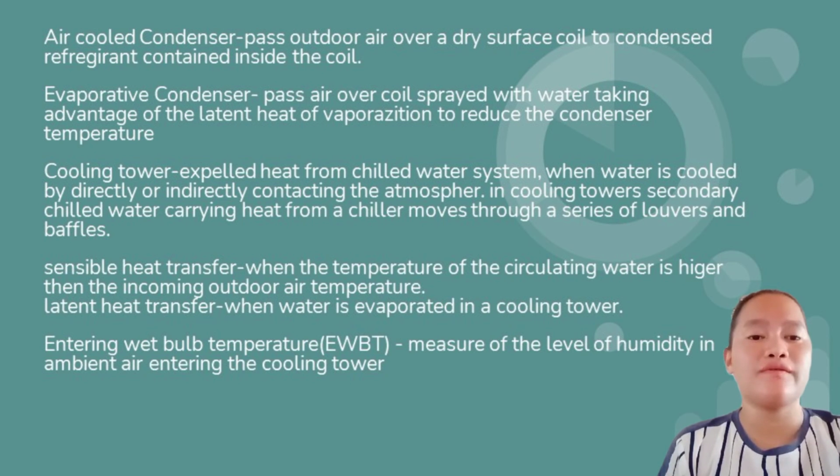Sensible heat transfer, when the temperature of the circulating water is higher than the incoming outdoor air temperature. Latent heat transfer, when water is evaporated in a cooling tower. Entering wet bulb temperature, a measure of the level of humidity of the ambient air entering the cooling tower.